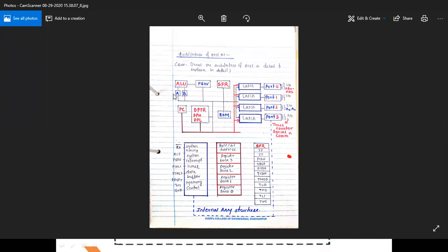Now see here, A register. A stands for accumulator. It is 8-bit long. It is a very important register. It is used in any arithmetic and logic operation. In any arithmetic and logic operation, the first operand should always be present in the accumulator. After performing the operation, the result is again stored into the A register. That's it. Look again, only 5 sentences about the A register.